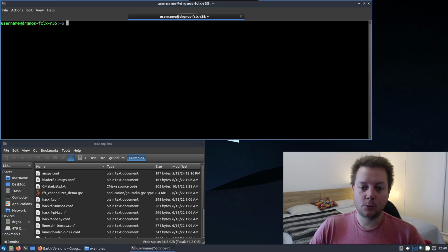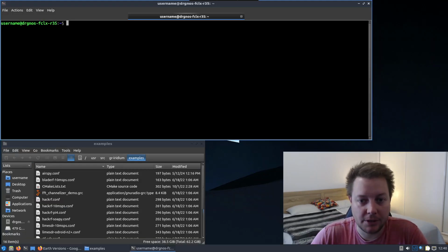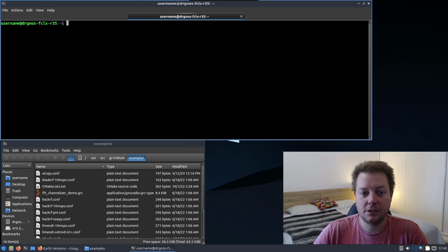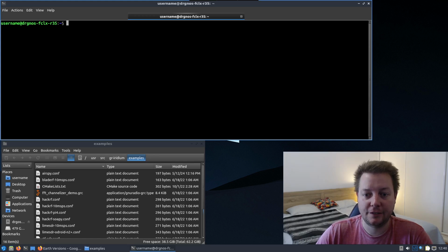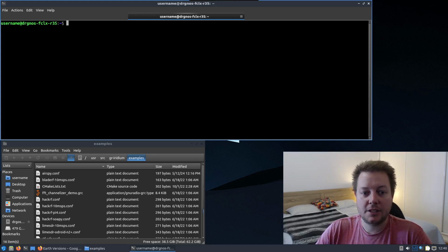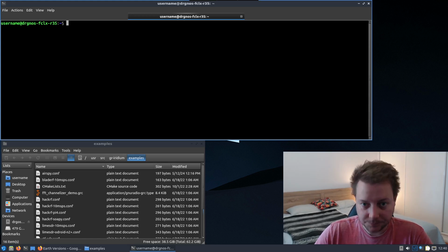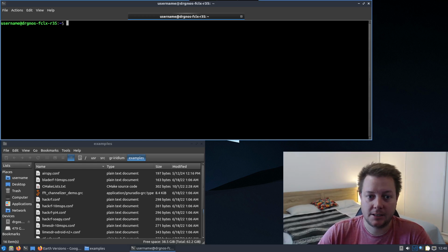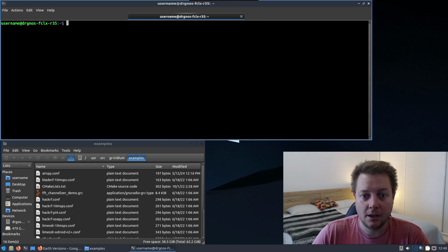Okay, first, before we can begin capturing Iridium data, we need to do a bit of configuration by editing some config files. gr-iridium is the first software tool we are going to configure. gr-iridium is the first stage in a two-stage process of decoding Iridium data. Basically how it works is it detects any Iridium burst signals that are entering the antenna. It demodulates them in software and finally writes the decoded burst to a file in your home directory.